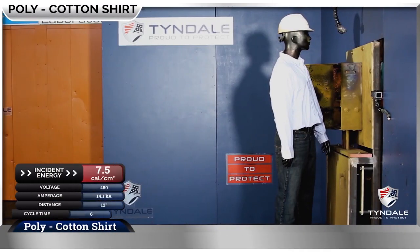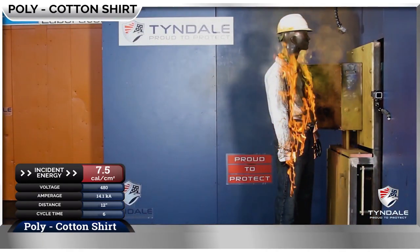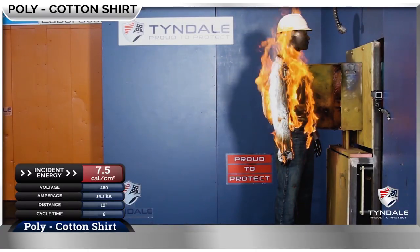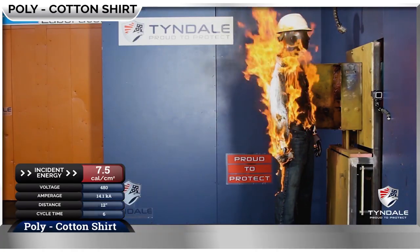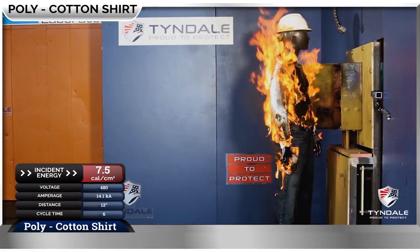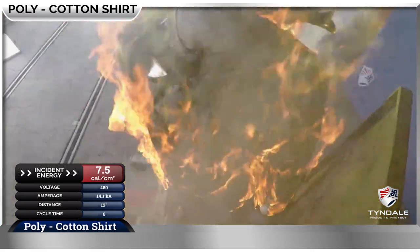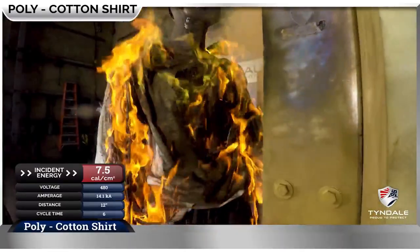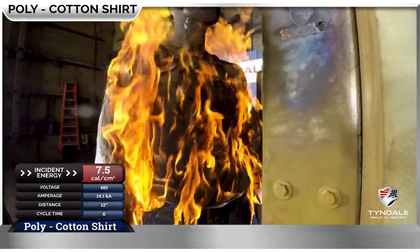This is polyester cotton clothing, a non-70E compliant mannequin in a Category 2R. As you can see, the consequences of this mistake are catastrophic. The garment is fully involved immediately, melting and dripping and shedding chunks. And look at how rapidly the back is fully involved. The entire garment, including the back where the arc never hit, is on fire. Our close-up front and side views will show the same thing in a little bit more graphic and close-up detail. This is not a situation that anybody ever wants to face. This is the consequences of wearing fuel rather than arc-rated clothing into an arc.